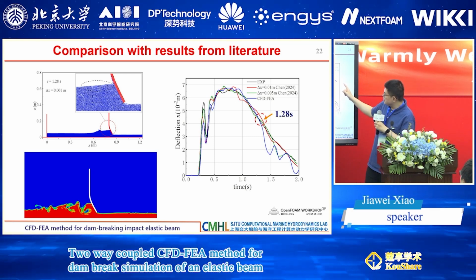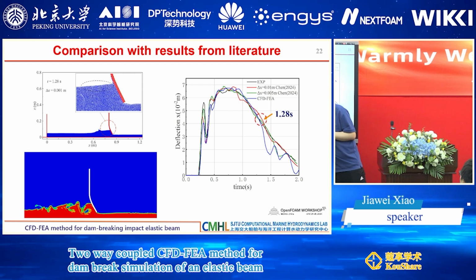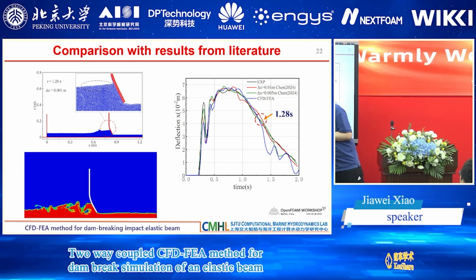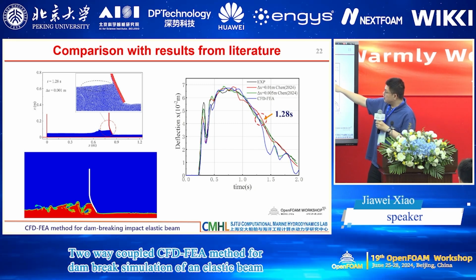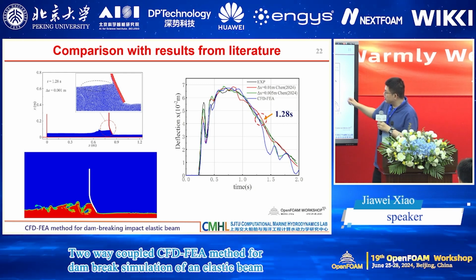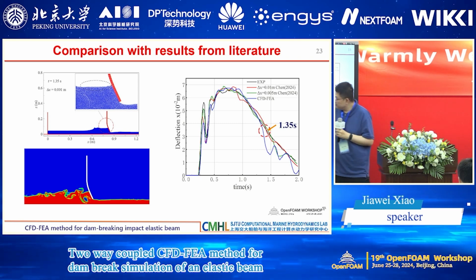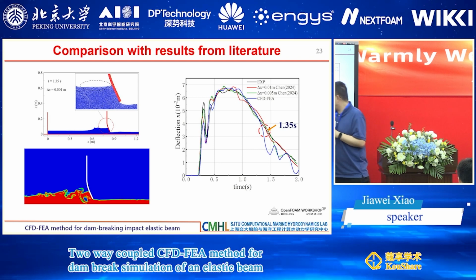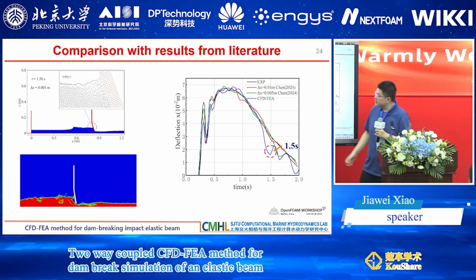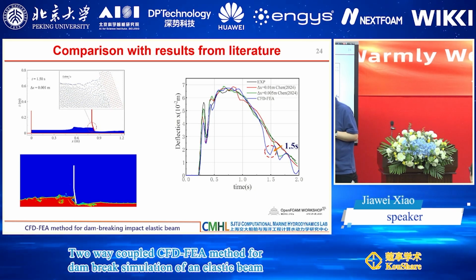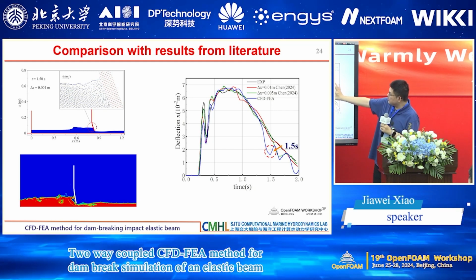And this is 1.28 the fluid field compared with the literature results. We can see that because the bubble didn't touch the elastic beam, the error between our simulation and the literature results is relatively the same. However, when it comes to 1.35, we can see as the bubble gets closer to our beam, our beam shows displacement escalation, and this is 1.50, and we can see the effects of our bubble, and we show escalation, and there is a large